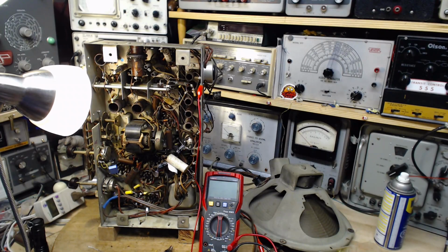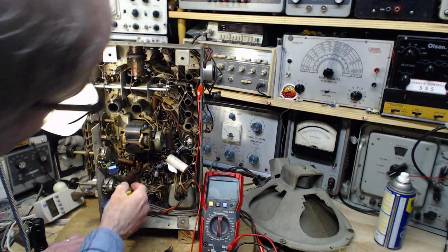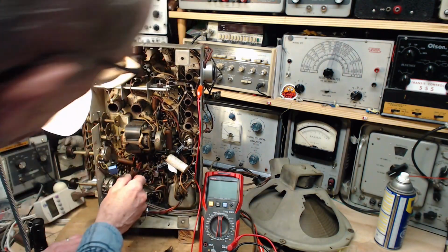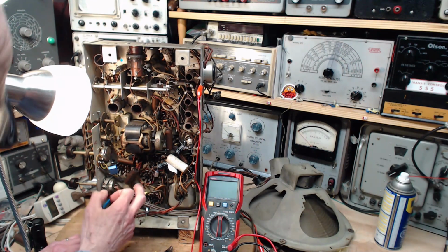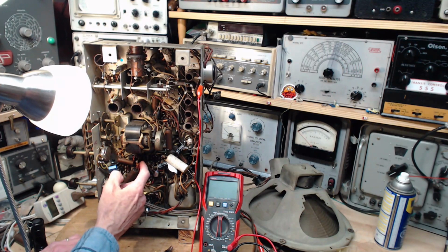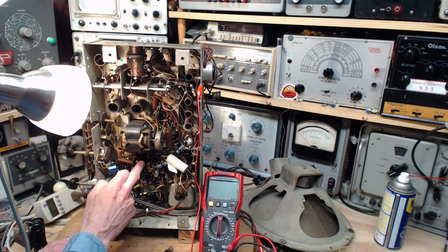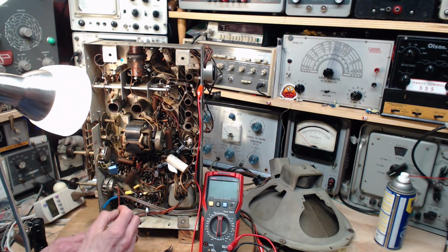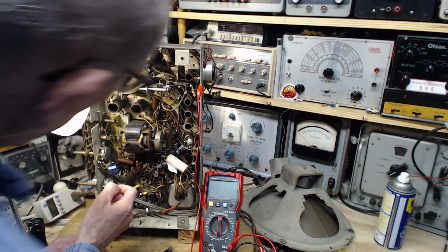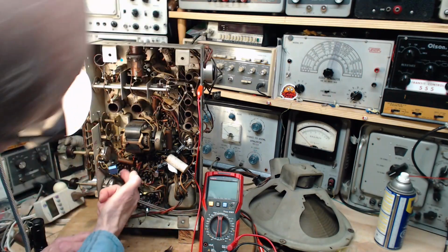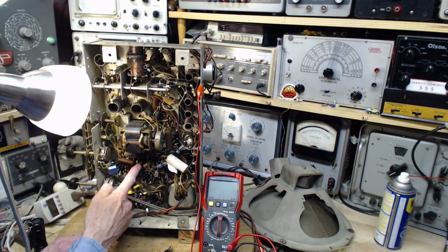Okay, back from Costco. Now, why don't we go after these two guys right here? This one is connected to one of the IF cans here. There's a lot of parts going in here, wires. Looks like red wires coming here, so this is probably a B plus point. It's probably the primary of the transformer. And then it comes over to this tube. I believe this is a ground point here. So it's a grounded capacitor coming off of this IF.